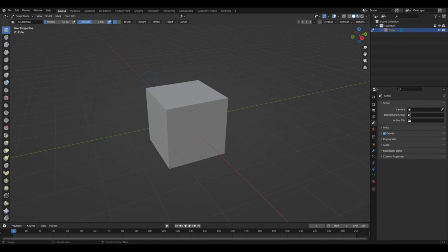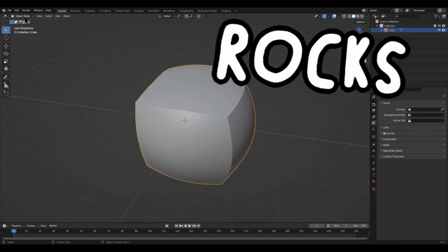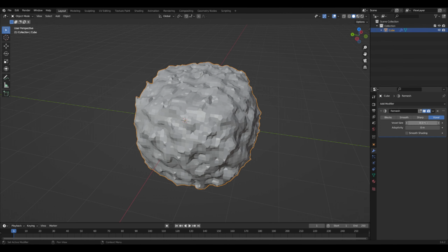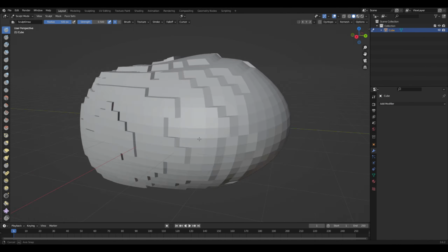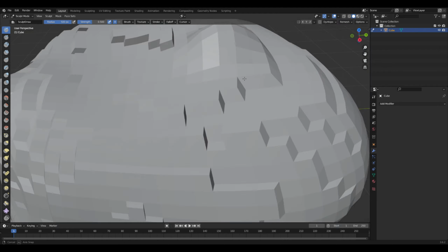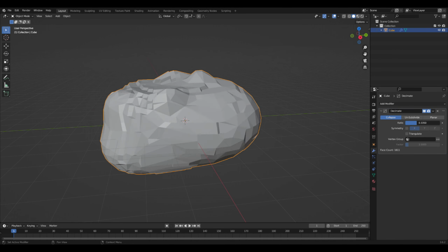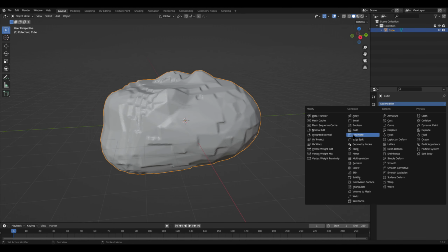We can then model some rocks by starting with either cubes or decimated spheres and using sculpting mode to flop around with them a bit. For more fancy applications, you could bevel the ends and then subdivide the whole thing for a smoother look.